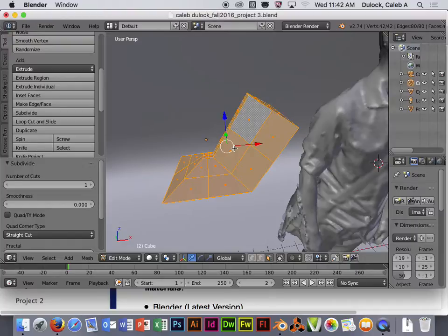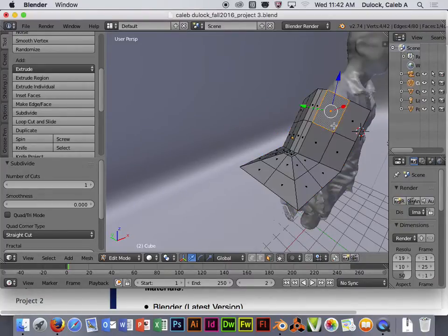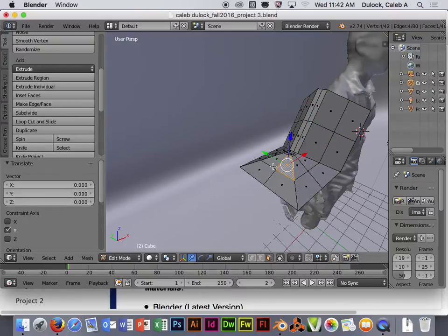You definitely don't want to do this on your whole model. Let me just warn you, because subdivision will break every polygon into 4 more parts, and that makes your model like 4 times as complicated in detail as it was, which could overrun your computer. So it's good to do it with individual sections or selections of things if it's really complex. But if it's simple, then it's easy enough to select the whole thing and break it up into a bunch of pieces. And now the cool thing is, now I've got all these little ridges and edges that I can make adjustments to.